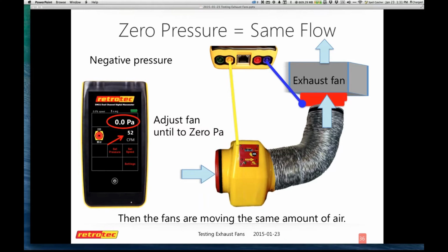Scott's original question was, when using the DucTester, does the flex duct need to be fully extended? Would it improve the accuracy? And my response to that was that in reality, we're not actually testing the flow through there, we're extrapolating from pressure, because remember, these are just manometers that are in the pressure gauge. No matter what gauge you're using, it has a manometer, and a manometer just tells you the difference in pressure between 2 points, and it extrapolates flow.